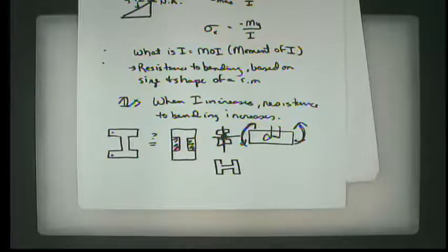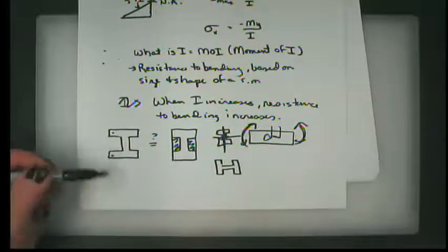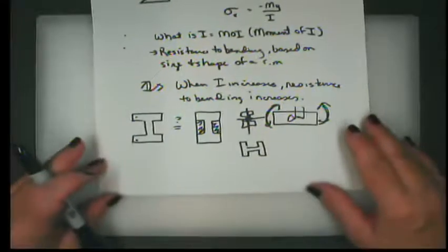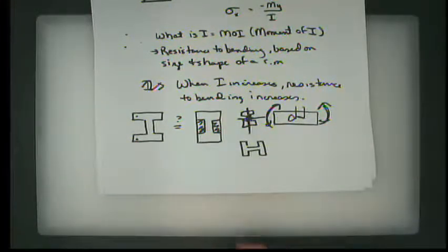Yes? The stiffness of the I-beam is even better than the raw material. Isn't that amazing? Because it's not weighing itself down. Yeah, and when they roll the shape, they can do some structural things with it. They're a wonderful design element. I agree with you. So the stiffness, which is another good descriptor for what moment of inertia does for us, is definitely much better for this shape.